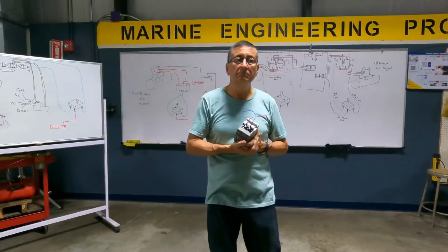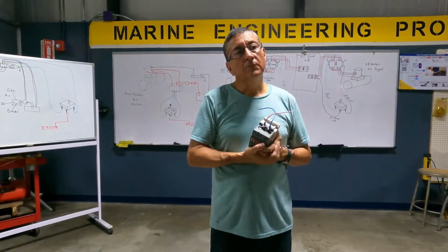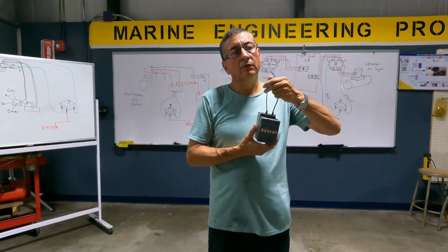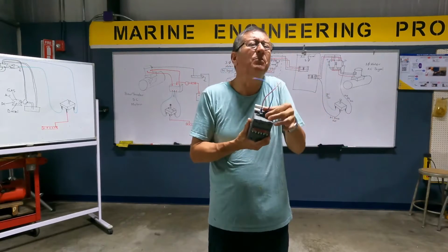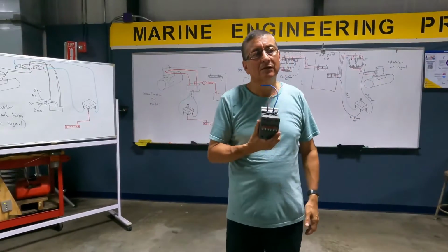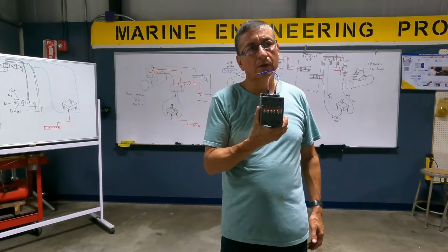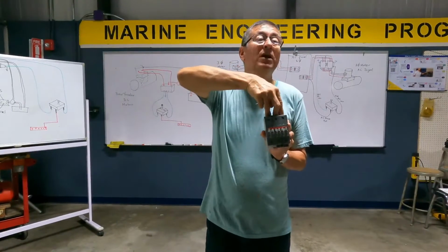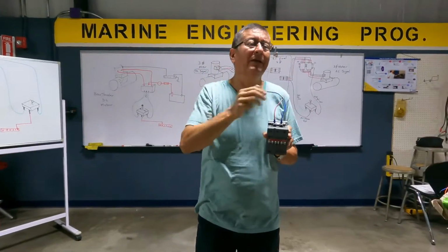The gauge of the wire is small only because it's not being activated for such a long period of time. Which one? The signal wire. So it's just a small amount of time. Yeah, it's a small signal for a short period of time. In comparison, you're running the same current through the bigger ones, but for a longer period of time, more amps. Here you can pass 100 amps, 200 amps. But here it is 5 amps or whatever. It's a small signal.